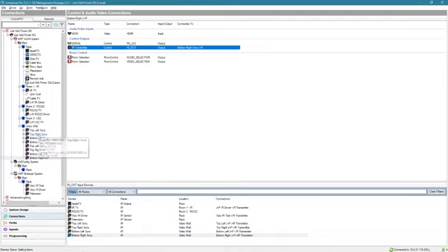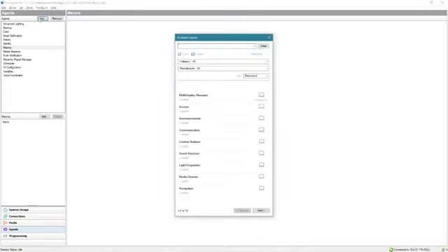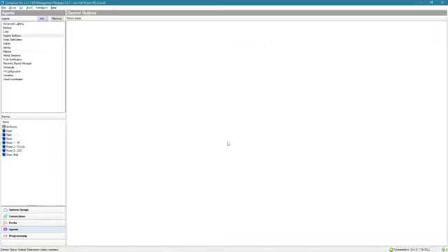So now that we've got all those connections, now we get to the video wall part. We're going to go to agents. We're going to make sure we have macros and custom buttons added to our system, because these are the things we're going to need in order to make the video wall work. Macros are going to do our into and out of layouts, and it's going to do our source switching, and custom buttons is going to give you the ability to actually put those macros on your interface.